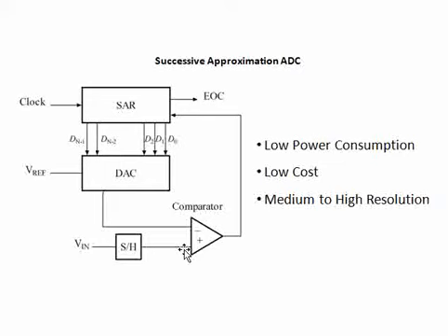we give a DAC output. So this DAC output, initially it will be at a specific level, and based on the comparison with respect to the input, this produces the control signal to this SAR ADC, and then successively the bits get changed, and again it gets converted to analog by the DAC.